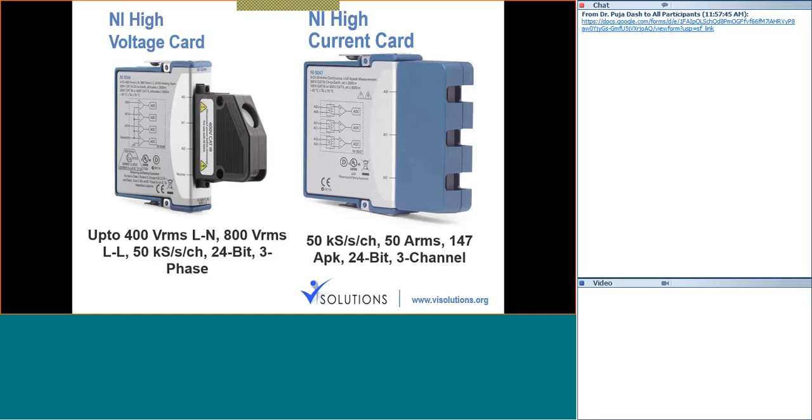Okay, so this is going to be very accurate, meaning any type of dynamic change also occurs. Since it is waveform acquisition, any dynamically changing values can also be acquired. So yes, it can go up to 400 volts RMS or 800 volts RMS line to line. If it goes above that, you may need to use a voltage transformer.